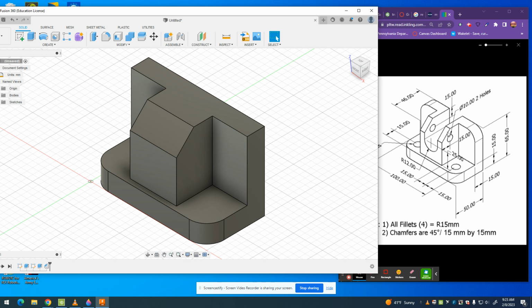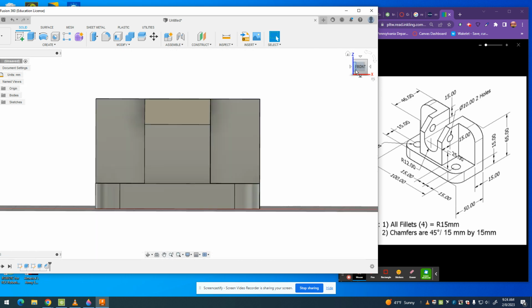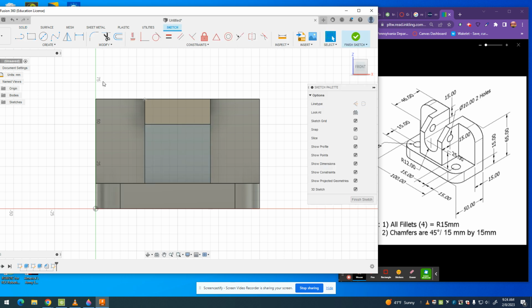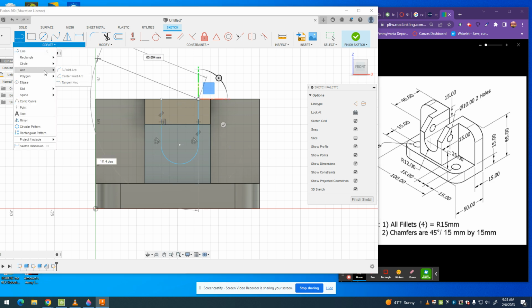All right, let's cut out this little thing if we can do that. So we're going to go here to our front view. And we're going to sketch on this front face here. I'm going to do a line coming from the edge, going down. And then there's a thing where if you like, oh no, that wasn't it. You hold both lines, you should be able to do a curve. So for those of you that are feeling snazzy, go for it. Otherwise, you would just do a 3-point arc, which is down here. Right? But I felt like it would be fun to do that.